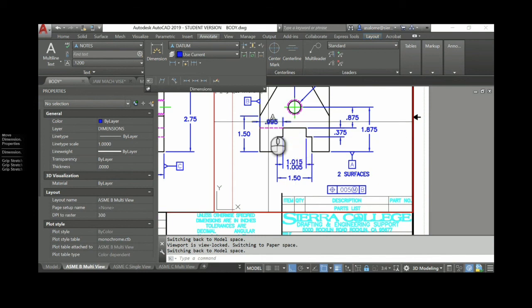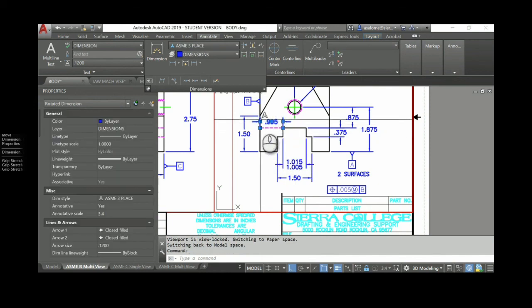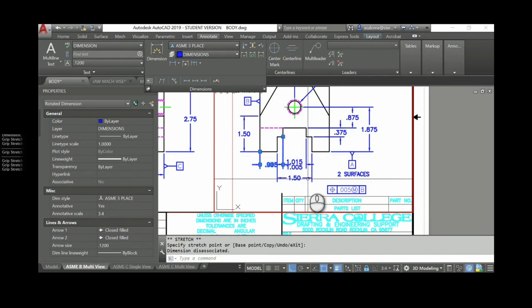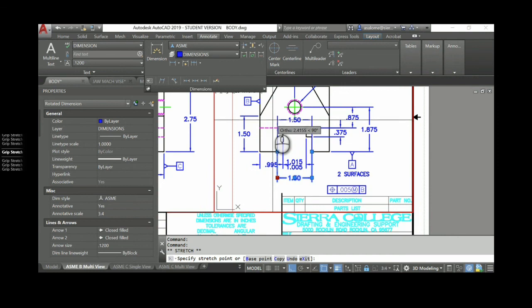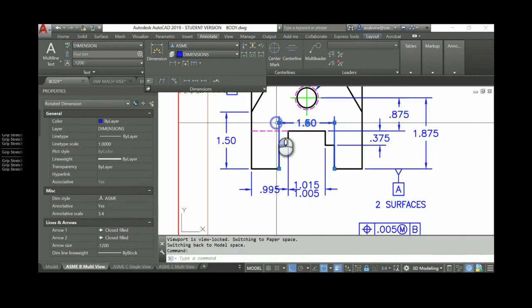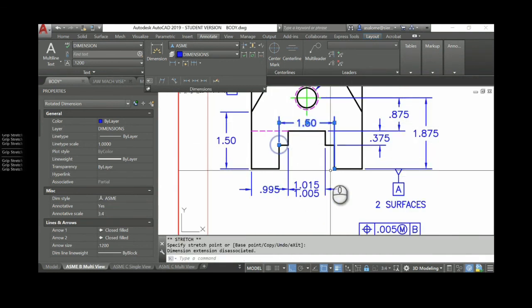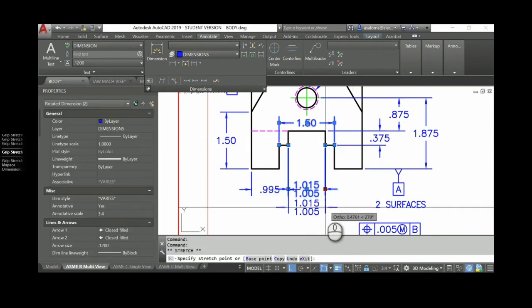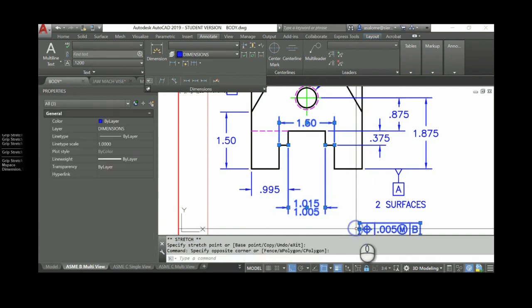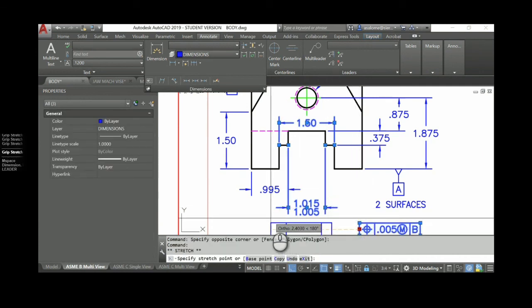So I'm going to take the 995 and pull it to the outside of the part, making sure I'm adjusting my O-snaps. And I'm going to take the 150 and swap it so that it's the one to the inside, adjusting my O-snaps. That's going to allow me to pull this guy down free and clear, which will allow me to move